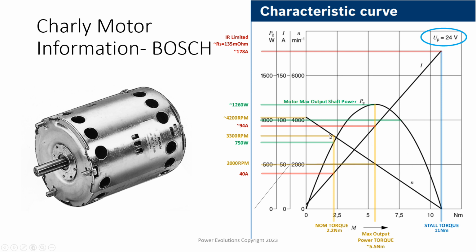However, when you're putting a model together, there are various things you can do for speed control which require you to know what that resistance is, and also what the back EMF constant is. But I won't bother going into that right now. So my limit on the controller will be 100 amps for the sake of it, and then we'll add some margin into that, so 125 amps, about 25% additional margin on the bridge.